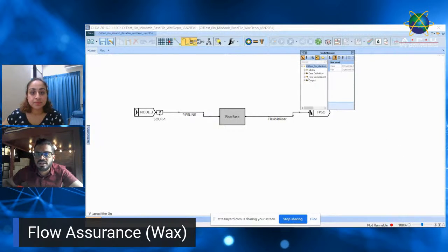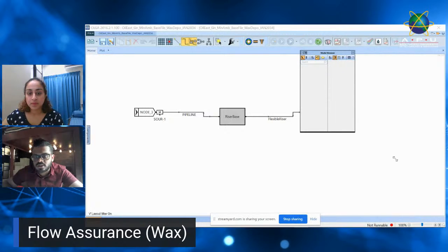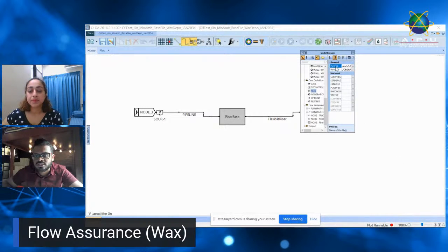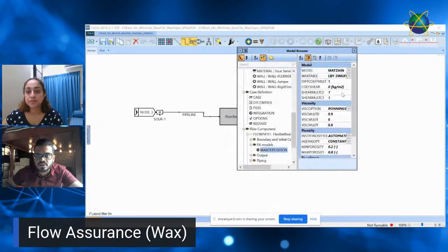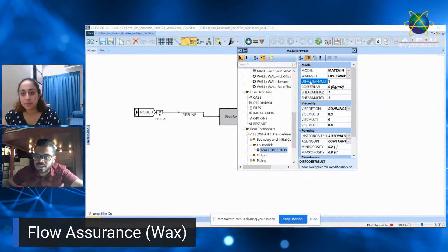Okay, cool. So if you look at this, let's look at the files here. Library. So here, all these files. Here we can input the wax file, and this is your PVT file. And then in terms of the modeling, you want to have a look at wax. So here we can actually specify this is a wax table. We can create all the fluid in PVTsim and then just import it into Olga. Yes, that's right.